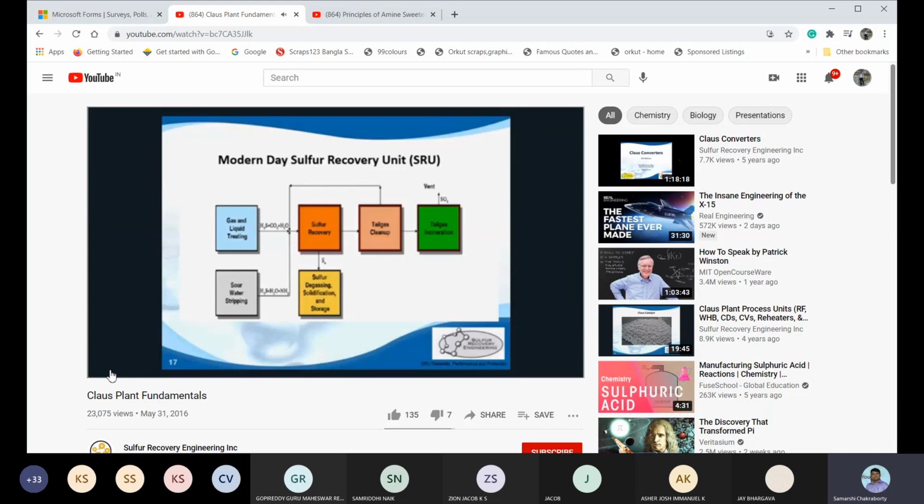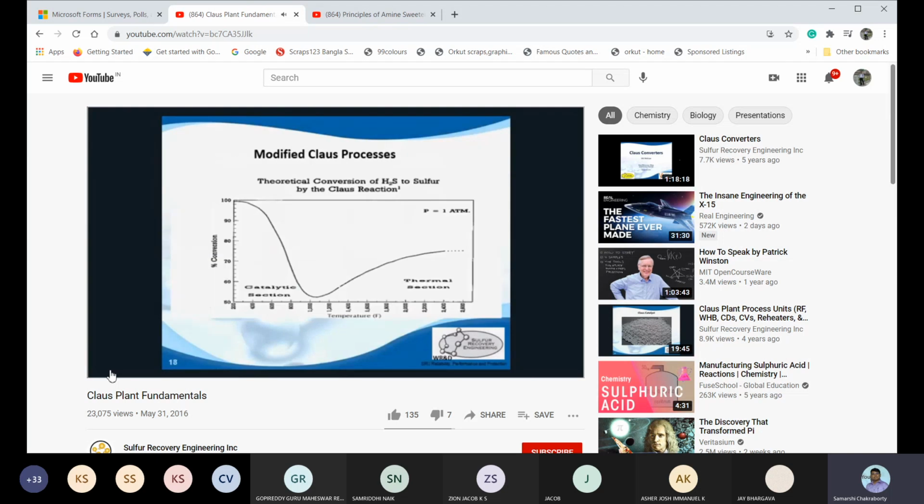And then we have incineration of our sulfur products that are turned into SO2 and vented out the stack. And then of course our product, our liquid sulfur, coming out the rundowns of our condensers. And that's degassed in degassing pits and then cooled and stored.